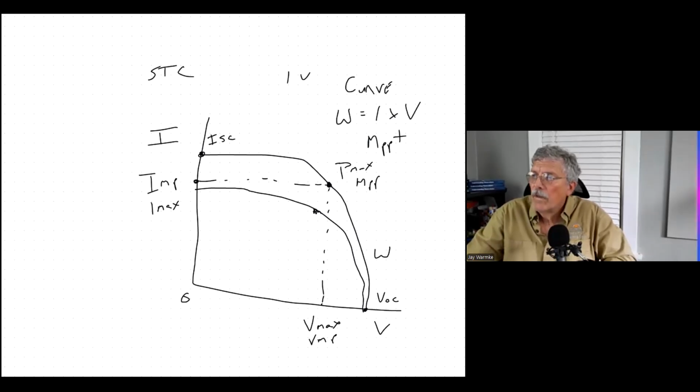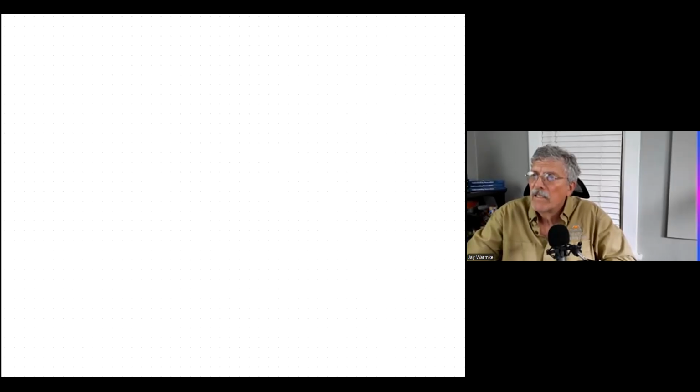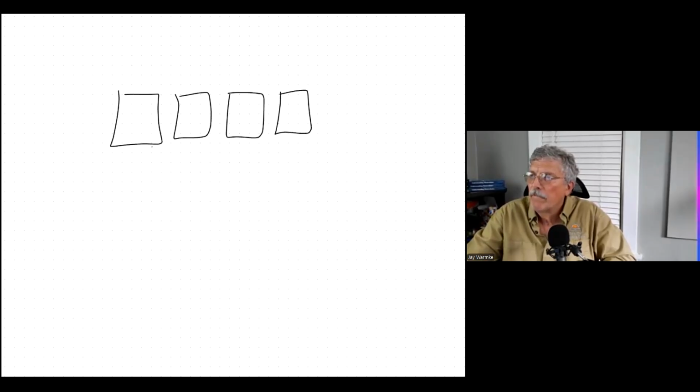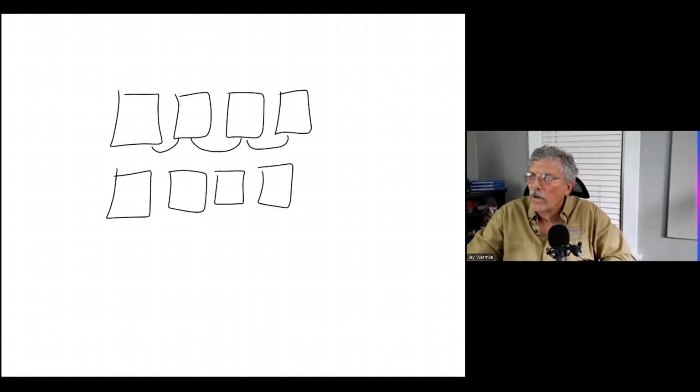So one of the reasons why, if I've got a series of solar panels all connected, let's say 4 panels connected in a string, and another string of 4 panels. You wouldn't configure it this way, but just for illustration purposes, a string is positive to negative and so on, so the voltage increases and the amps remain the same.